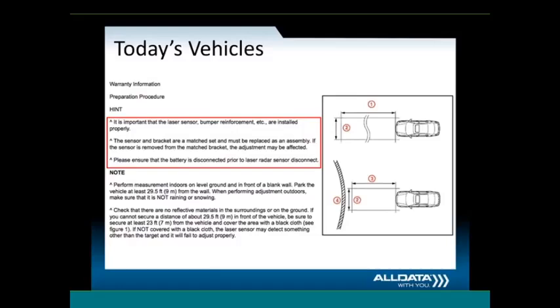Okay, so now we have a much larger supplement. And we have just added 2 additional days of this repair. Because the vehicle needs to have the adaptive cruise control laser sensor recalibrated using a factory scan tool. So if you have one, that's awesome. If not, you have to take that to the dealership and have that recalibrated. Okay?